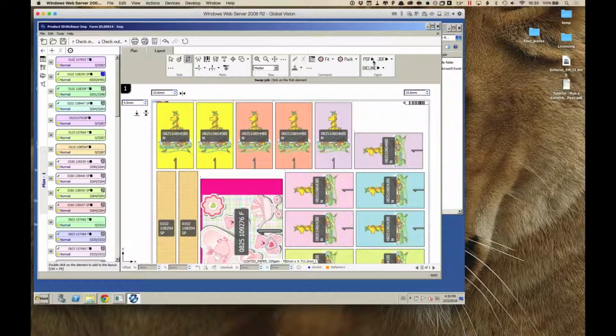From there, I can export a PDF file, an imposed PDF file, and I can export JDF, which can either be imposition JDF or cutting JDF, or I can export an explicit die line, either in DXF format, for example, or for some devices, such as some of the laser cutting devices, HPGL cutting information.